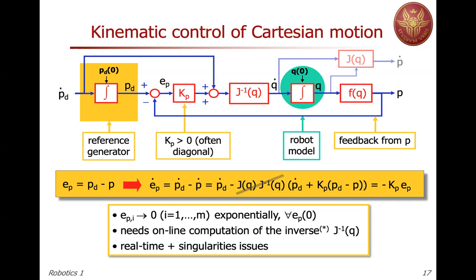It's moving on a plane xy, so either you control by feedback q1 and q2, or you control by feedback x and y. But you may also introduce a rotation on the end effector, and you would like to decouple the behavior of the error not along x and y, but along the x and y axis of a rotated frame. You have to include a rotation in this expression and do the computation.